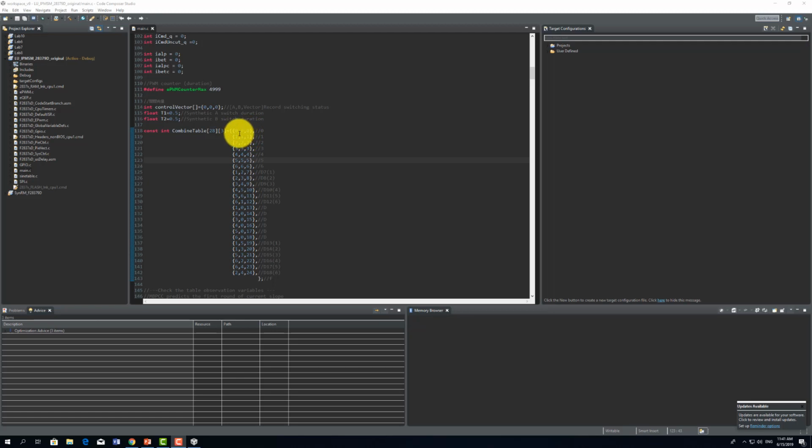The first two parts here include the voltage vector and the voltage vector combination, and then the last part corresponds to the switching state. For example, in the operation later, in the combination of two voltage vectors like voltage vector 4 and voltage vector 0, the switching state is equivalent to 16. The same thing on the last part. For example, if we have the combination of voltage vectors 2 and 4, then the switching state is 24.